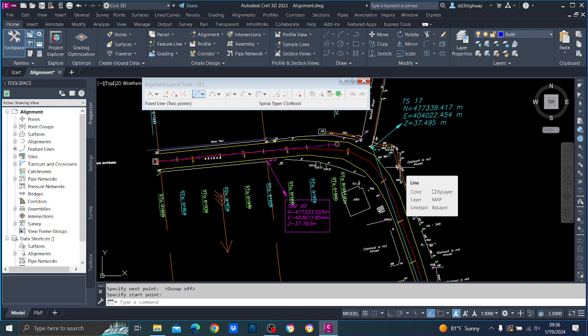Now superelevation: your book gives superelevation up to 10%, but please remember in urban areas we go only up to 4%, not beyond. So for 4%, if I remember correctly, your minimum curve radius is 90 meters. Check it. 50 kmph. Is it 90? You don't know where it is. Give me this one. Very good.